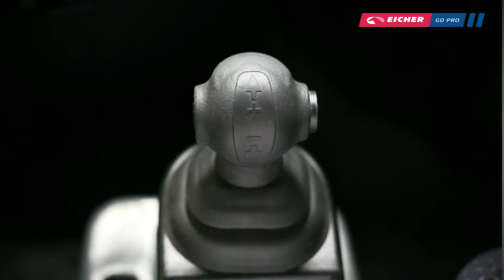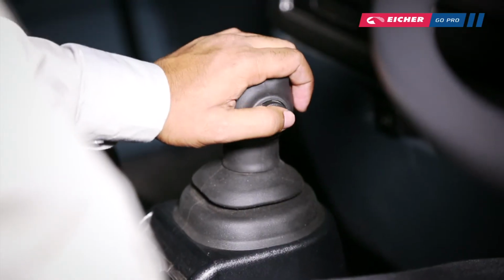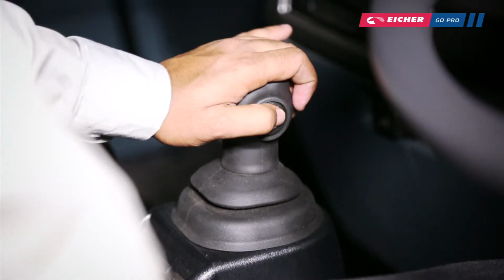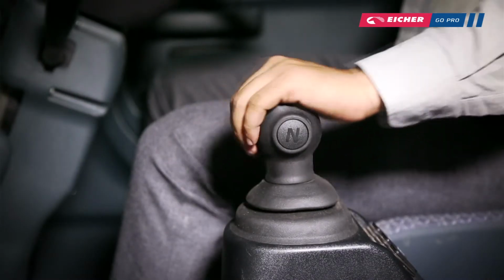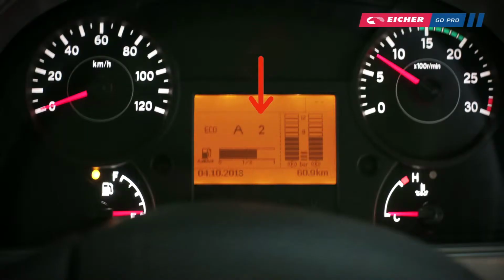When the vehicle is started and the gearbox is in neutral, forward start gear is requested by pressing the function button F of the shift lever unit and simultaneously moving the shift lever forward. Second gear is the highest available gear as starting gear. A shift request to a gear higher than second gear as starting gear will be rejected.